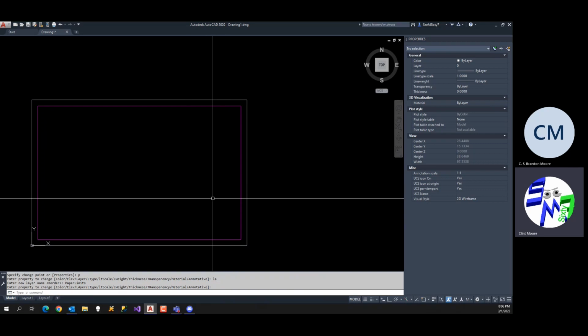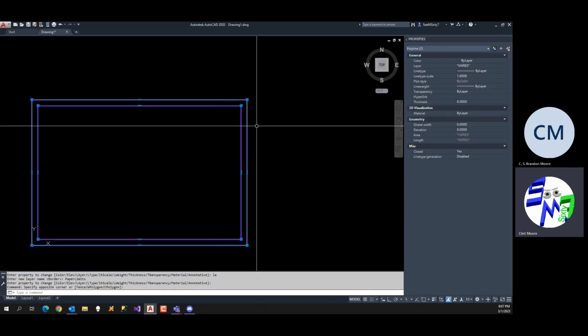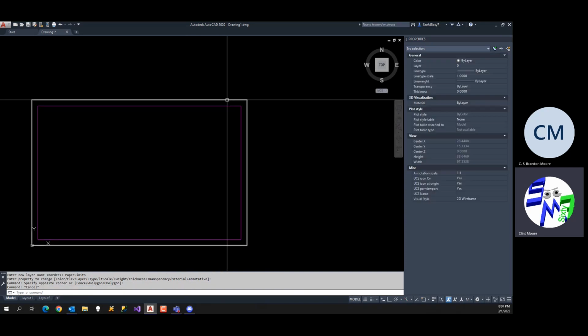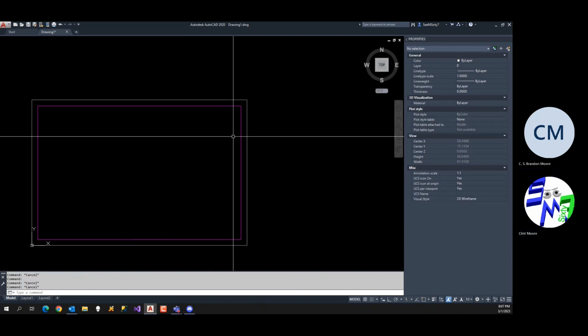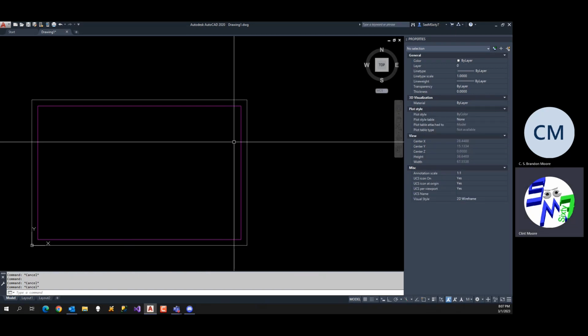All right. So there's lots of ways you can do things in AutoCAD. You can use the dialog box, or this is actually a palette, the properties palette. This is something you will commonly use a lot, because when you highlight things, you can manipulate common properties. If you highlight multiple objects, or one object, you can manipulate certain properties there as well. Okay. So again, get familiar with the command line and understand how to actually use it to make things happen.